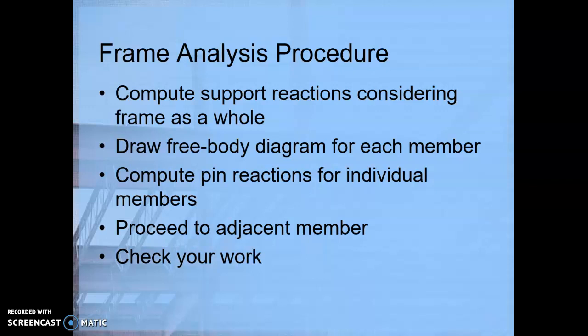And the way that we do that is not by a method of joints like we did with truss analysis, but instead we are going to look at each structural member individually and draw a free body diagram of it and calculate the reactions at the ends or joints of that particular member. And once we have found what those reactions are, then we can move on to the next member.